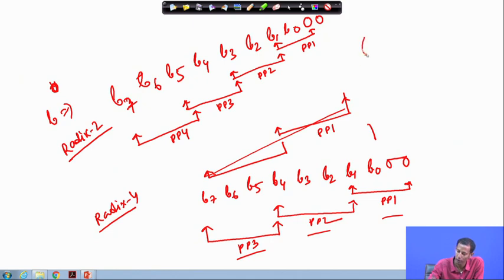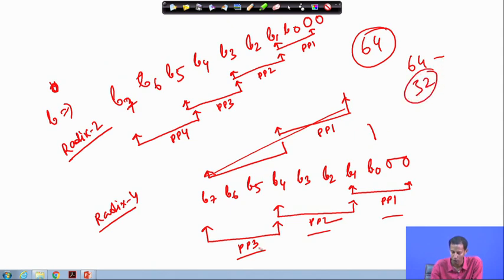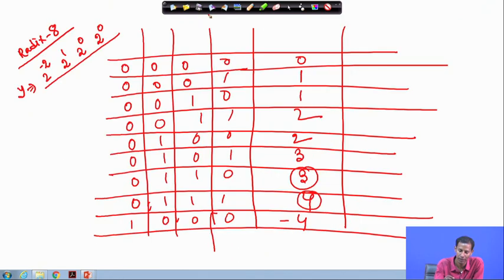So, the more the number of bits we consider, that means if we consider 64 bit multiplication or 32 bit multiplication, at that time I need to use, this is for Radix-4, this is for Radix-8. So the higher radix I can choose for Booths decoding. But the thing is that, as in the previous case, I will get 16 combinations and I need to generate these partial products from the beginning based on the corresponding set.